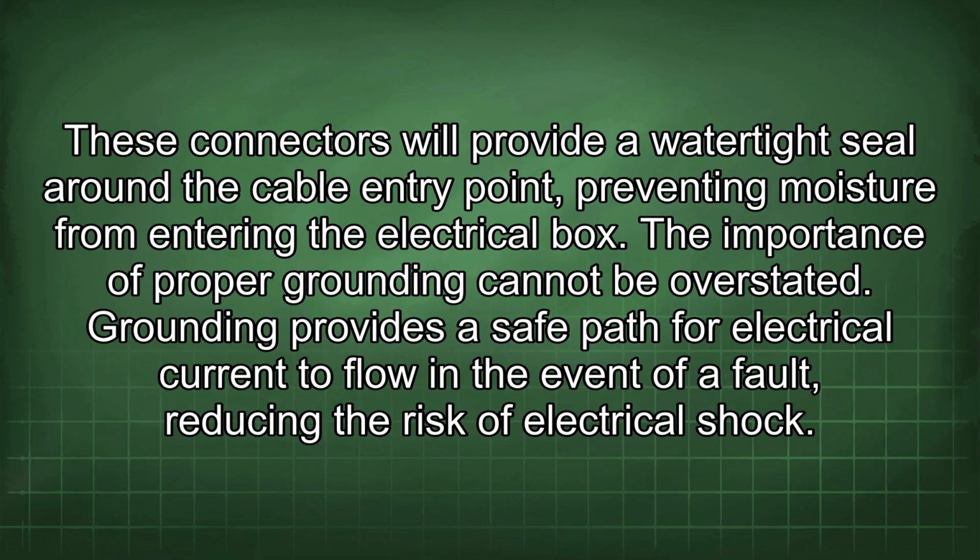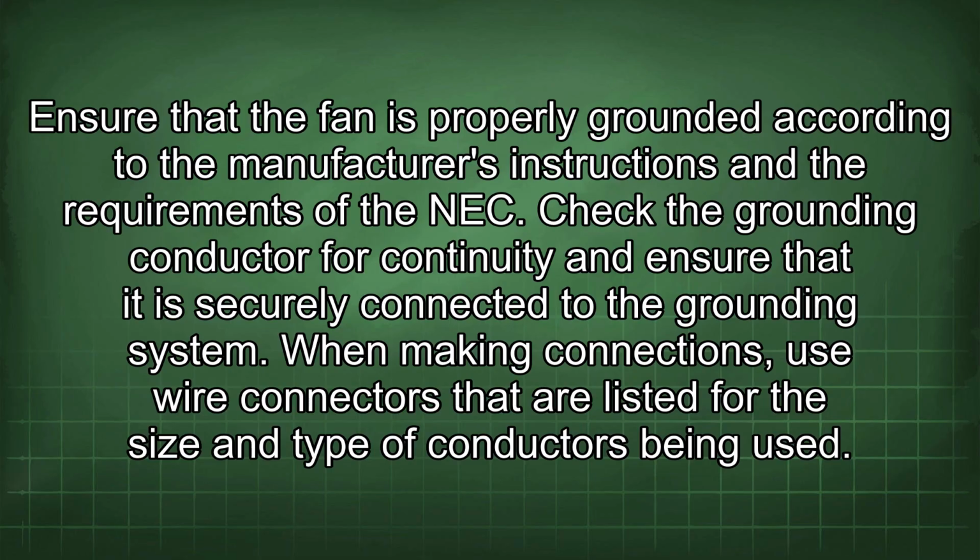The importance of proper grounding cannot be overstated. Grounding provides a safe path for electrical current to flow in the event of a fault, reducing the risk of electrical shock. Ensure that the fan is properly grounded according to the manufacturer's instructions and the requirements of the NEC. Check the grounding conductor for continuity and ensure that it is securely connected to the grounding system.